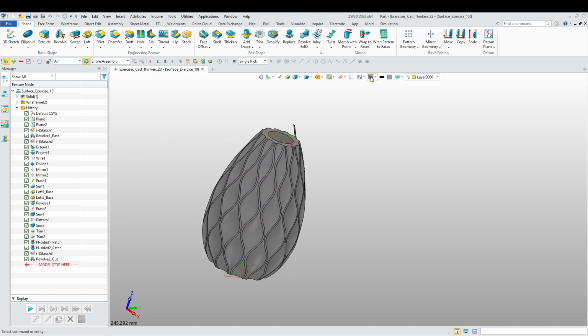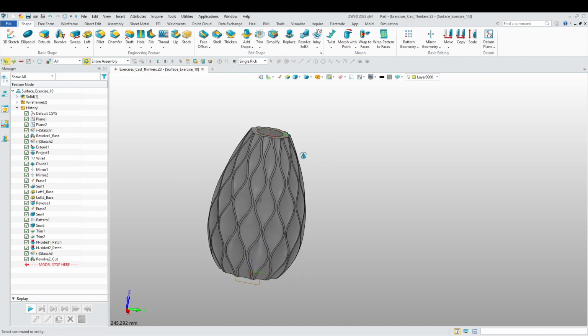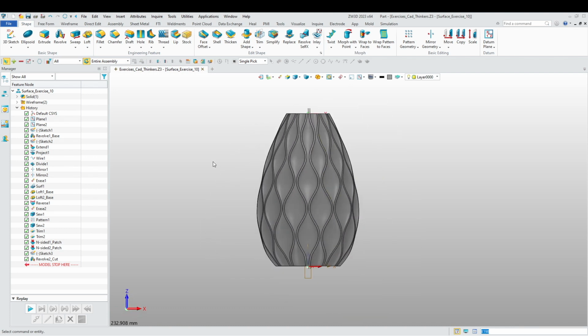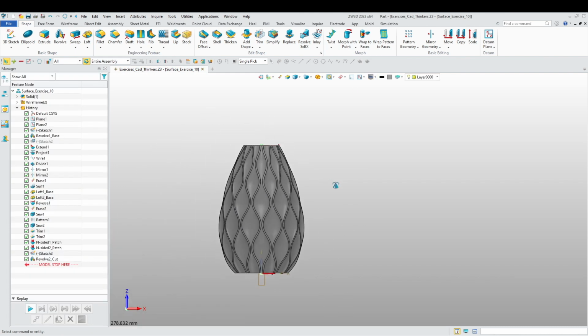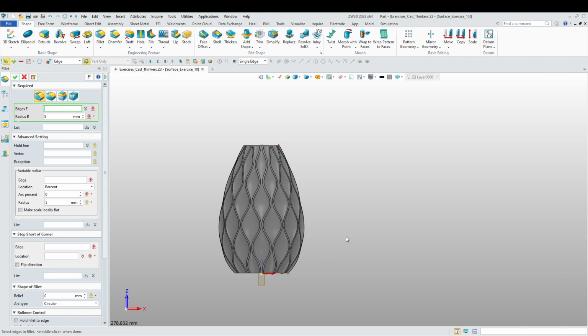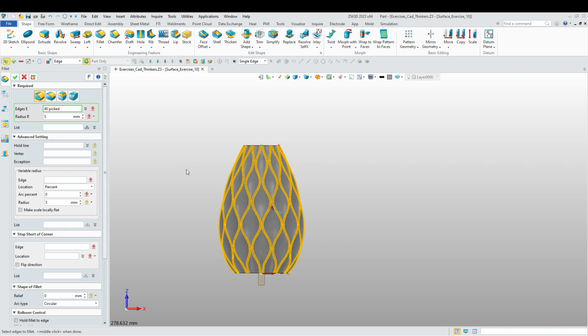We are almost finished. Now just going to finish off with the fillets. All right, so let's add some fillets to this. Okay, fillets, I want to choose all these edges. And I'm going to say it's 1.75. Okay, good.